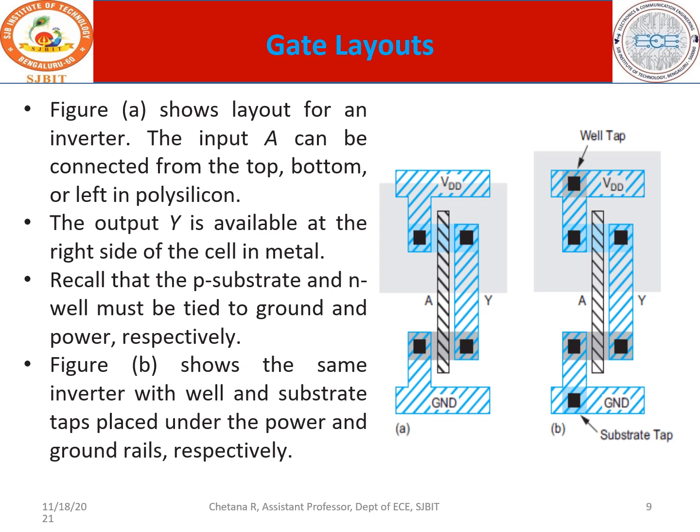You have P diffusion in the pull-up region, N diffusion in the pull-down region, and vertically the polysilicon, so a transistor is created. This is the transistor. Polysilicon is your input, this is your input A, and if you notice, the two drains are shorted. This is where you have Y. The source of PMOS is connected to VDD and the source of NMOS is connected to ground. So this is the layout representation of an inverter.